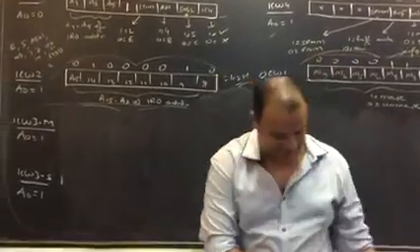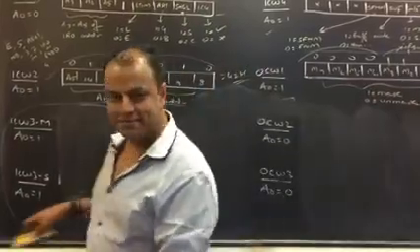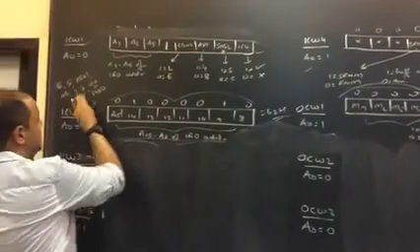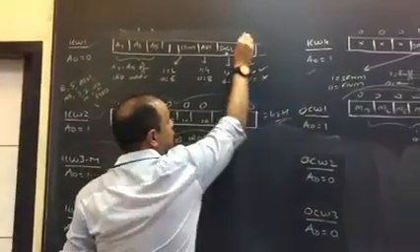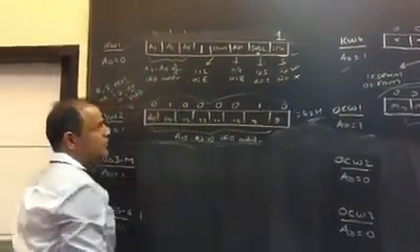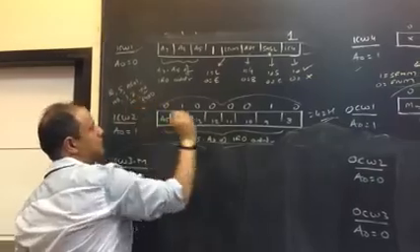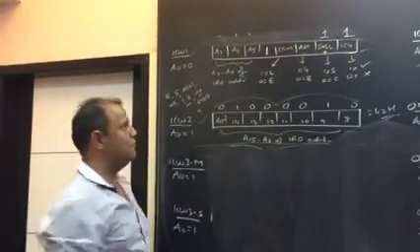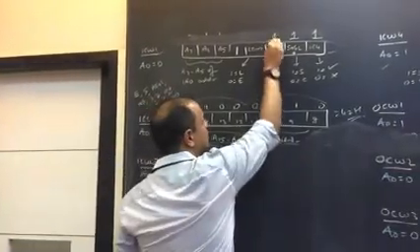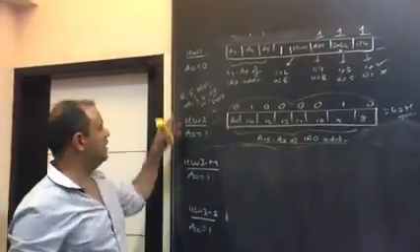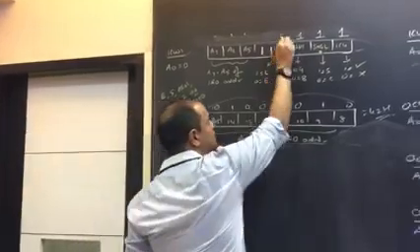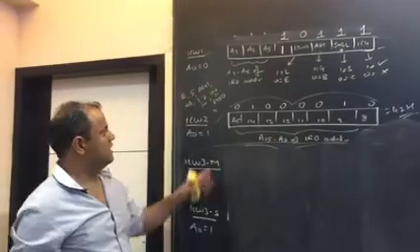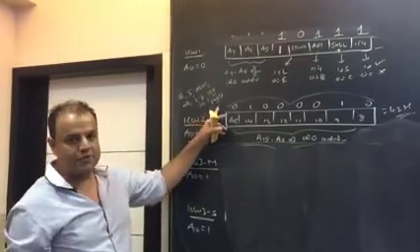Let's form the commands. Come on, don't be scared. First, ICW1. Do we need ICW4? Yes, because it's auto EOI, so we will be giving ICW4. They've said it is single. Single means this bit will be 1. They've said address interval is of 4. 4 means this bit will be 1. They've said what triggered? Edge triggered. Edge triggered means this bit will be 0. This bit is a permanent 1. ISR address of IR0 is 6980.